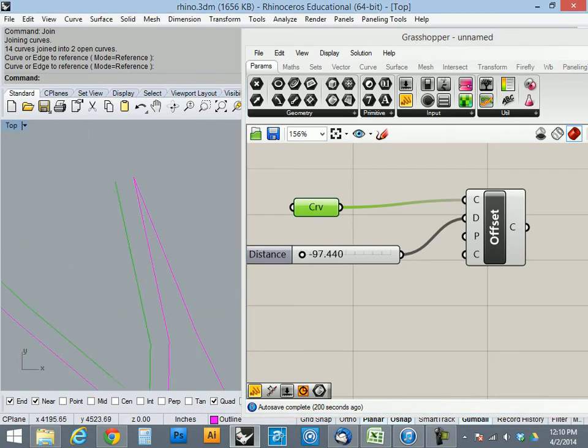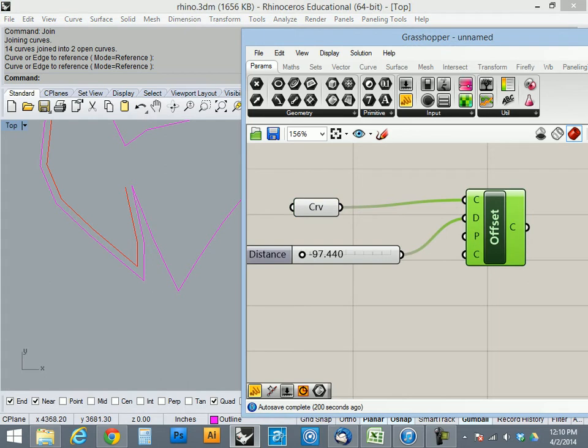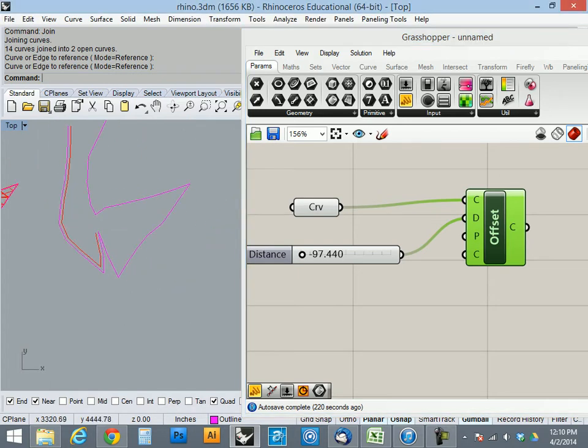Alright, so let's just look at this for now. Now we have this offset curve, and basically what we want to do is now put points on there. The points are going to be what we reference in the CNC machine as drill points. So those will be plunges. Okay. Now the tricky part is lining up the holes with the other parts of the pattern, right?